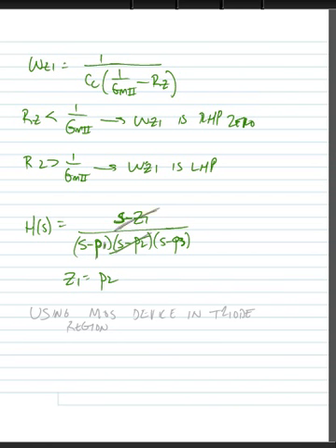So our strategy is going to be to do just that. We'll set the value of our zero to be equal to the value of the second pole in our circuit, such that we get the largest separation between the two remaining poles, omega P1 and omega P3.